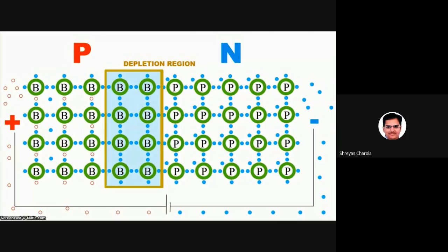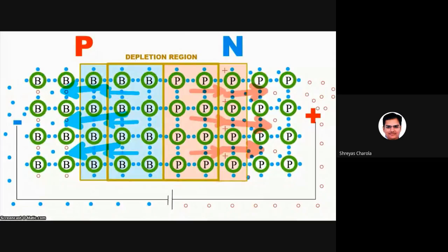Meanwhile, the positive side adds holes to the p-type silicon. The p-type crystal now has a massive excess of holes, which are all attracted to the massive number of electrons in the depletion region. So the extra holes come to the electrons, and the electrons hop over from their previously neutral atoms to the extra positive holes and cancel them out instead. The electrons are sucked out, the depletion region gets smaller and might almost disappear with a large current. So we see that in a PN junction, electric current flows in one direction but doesn't flow in the other.